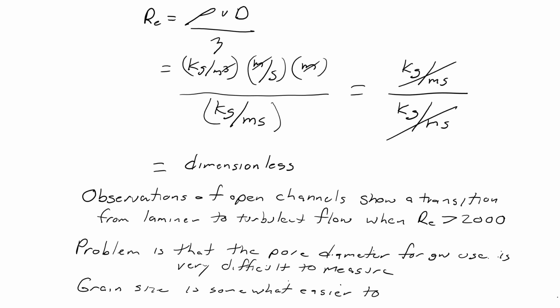We know the average size of clay. So we have measurements for the grain size. And in general, the bigger the grain size, the bigger the pore. If you think about how gravel would stack together, they would have much bigger openings in between than little tiny silt particles or clay particles.